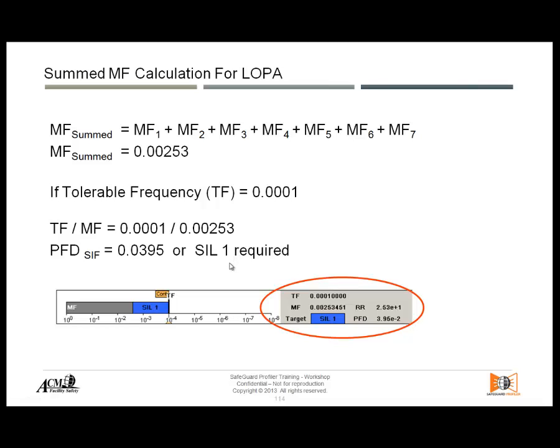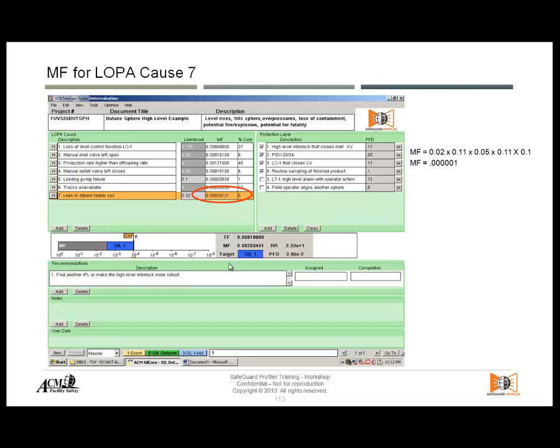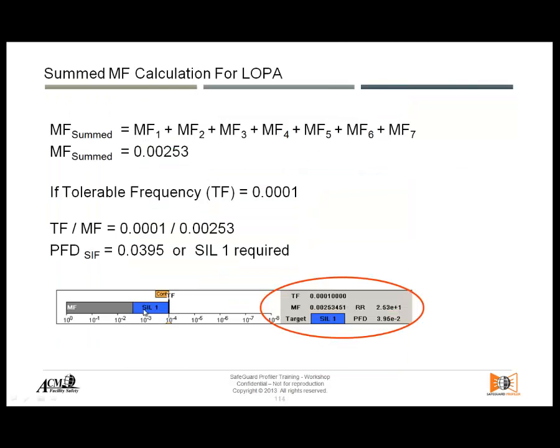So we will see what that means in this case if I already used this high interlock level that closes XV. This is supposed to be my safety instrumented function that I had there before, and I can see that today this safety instrumented system is not enough. I still have a gap of SIL 1, so I would have to come back to this safety instrumented loop and make it better, because today I have a gap there.